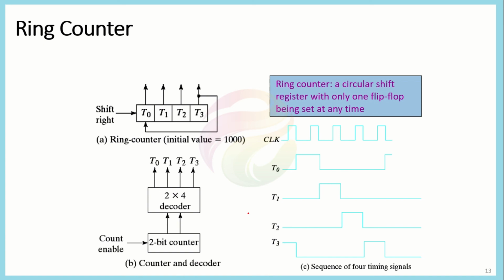Say we have a count enable pin that is attached to control this shift operation. Then a 2-bit ring counter would be producing 2 different kinds of output. It would have one equal to 1 and the other equal to 0. Then it would have the first one equal to 0 and the other equal to 1. Then we could use these outputs to control our decoder. We could combine them in the form of a 2 to 4 decoder, and for the 2 to 4 decoder we could have a value against each of them at a certain time.